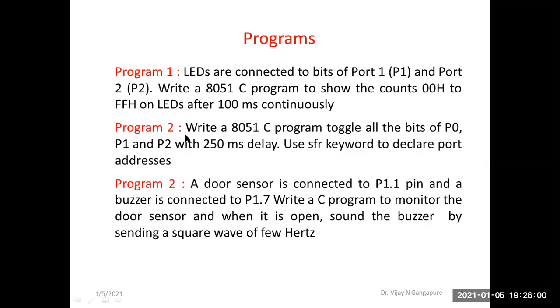The second program is: write an 8051 C program to toggle, okay, 2 is missing here, to toggle all the bits of port 0, port 1 and port 2 with 250 millisecond delay. Here it is specially asked to use the SFR keyword to declare port addresses.